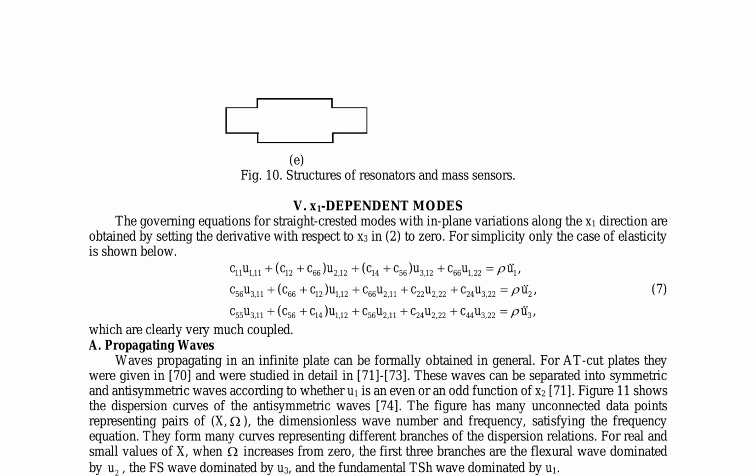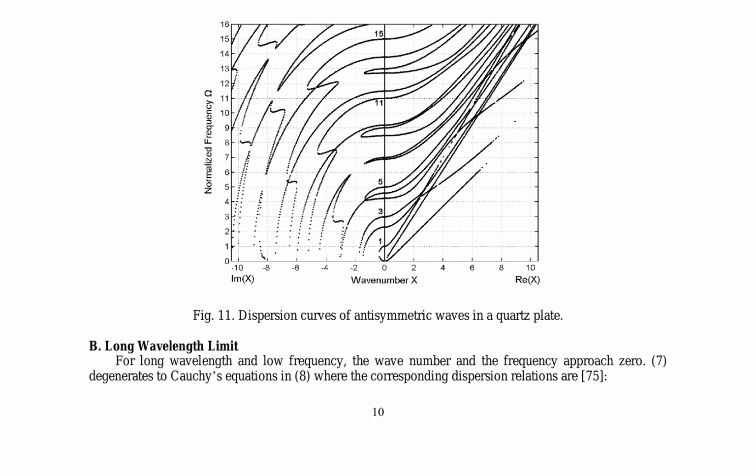The research focuses on X1-dependent modes, particularly the governing equations for straight-crested modes with in-plane variations along the X1 direction. It presents a simplified case of elasticity, demonstrating highly coupled equations. The paper then explores propagating waves in an infinite plate, which can be formally obtained in general. For AT-cut plates, these waves are studied in detail, separating into symmetric and antisymmetric waves based on whether U1 is an even or odd function of X2.